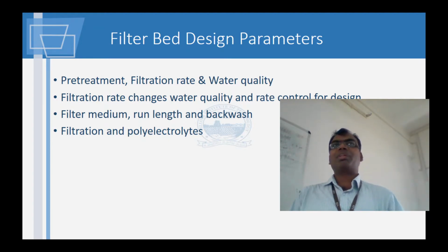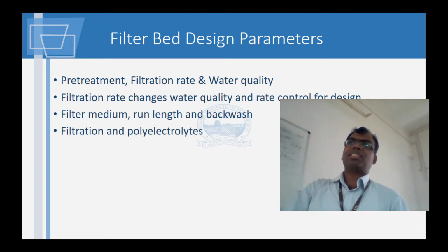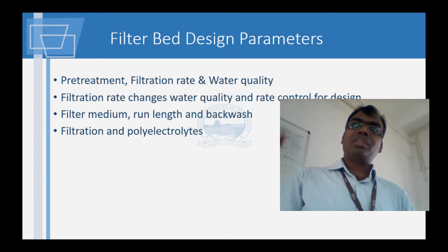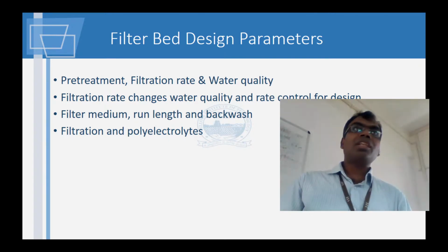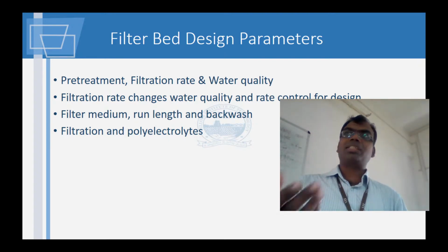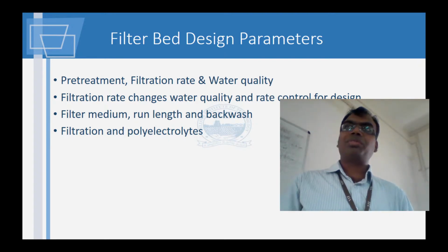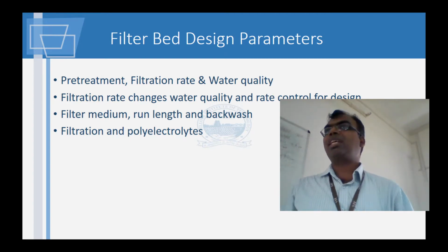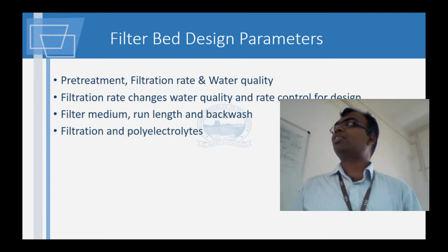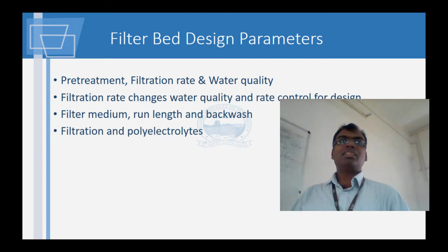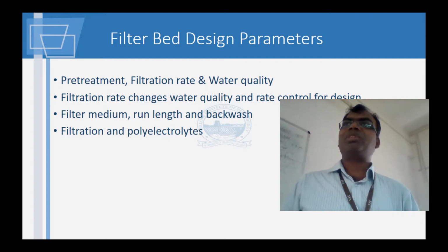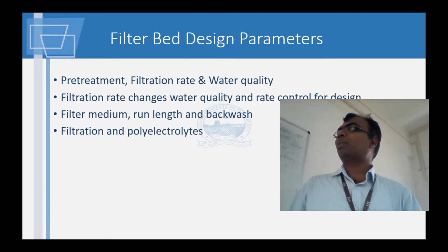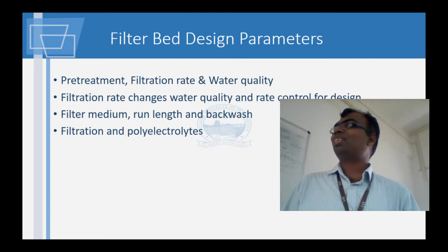Suppose I am going to require very fast filtration to take place. Again, take for instance the example of your tea strainer. If you are using a strainer with larger holes, the milk is going to flow at a rapid rate. But what will happen? There's a chance that some cream particles can go through. Same thing, instead of cream particles, you'll have whatever material is given. So what you expected to have been stopped is not. So this is a very simple example.